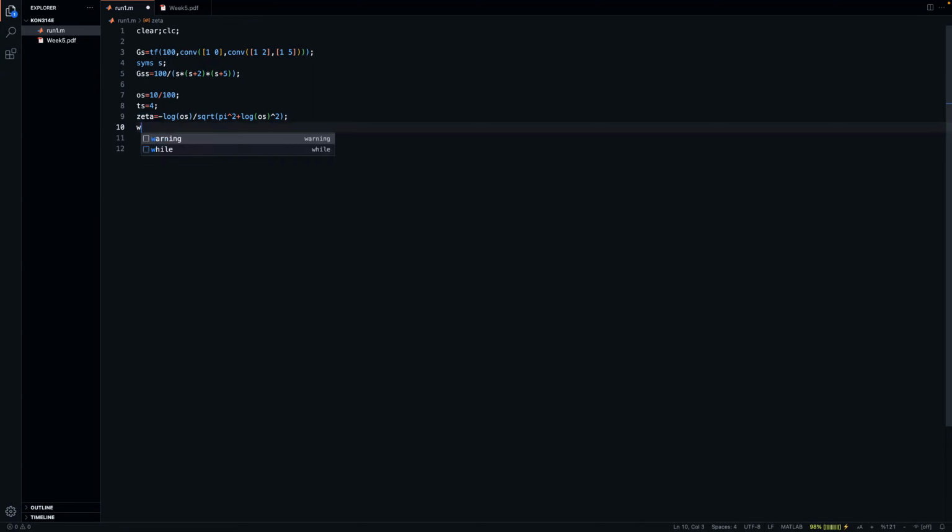Since we know that, we can use Ts equals 4 divided by zeta times omega n. We can manipulate this so that we are calculating omega n. And here this should be Ts. Since I have them written down like that, this should be automatically calculated here. So when I know zeta and I know the settling time, 4 divided by the multiplication of them should give me the omega n value. So I know exactly where I want to place my conjugate pole pair on the S domain.